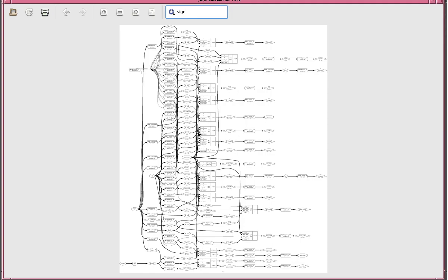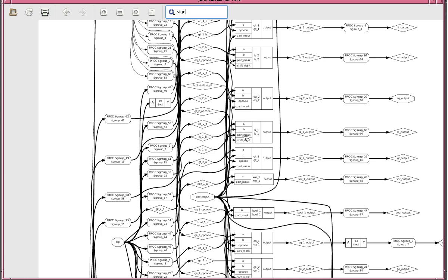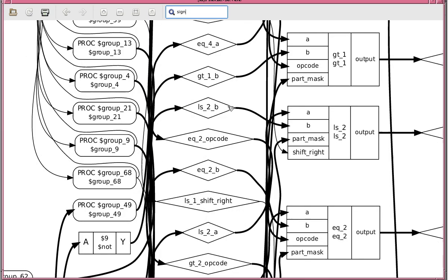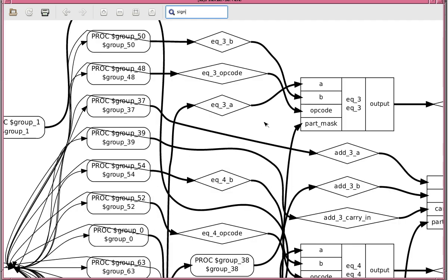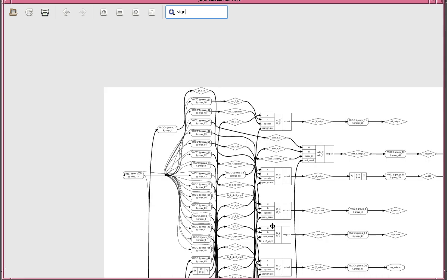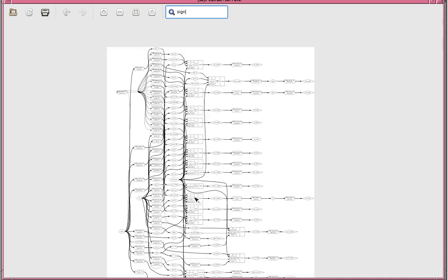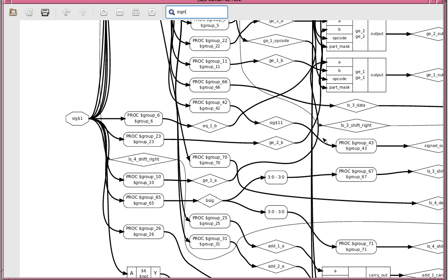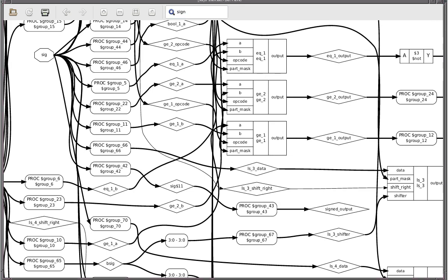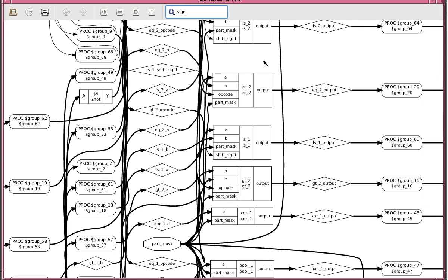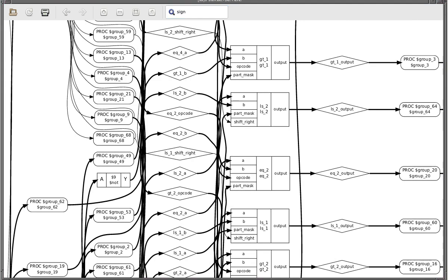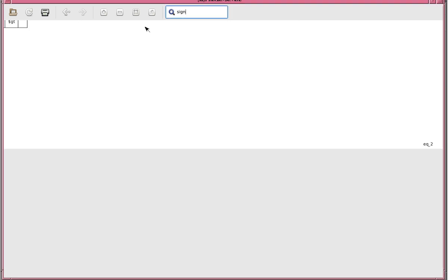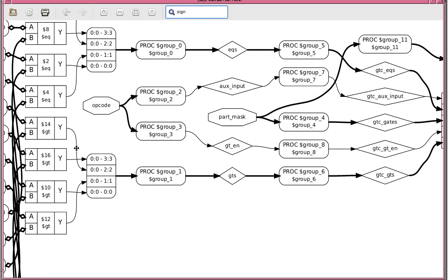Okay. So this is a diagram of a partitioned signal module which we're developing for LibreSOC to do automatic SIMD, and this is a Yosys show top command on one of the test benches, and you can see we've got modules here, for example there's a greater than or equal test as part of it, etc. And if I do an additional command, show EQ_2, we can see that this is doing a partitioned equal.